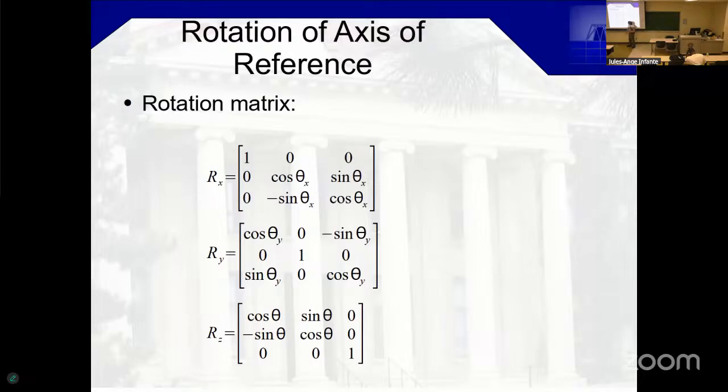So this is theta Z and theta X, theta Y. And this is around on the horizontal plane, but this is on the X plane and the Y plane. Okay, the two vertical walls. So you can rebuild them yourself if you want to compare to verify that we're getting to the same, but it would be a similar type of construction. Okay? And by placing things in the order X, Y, Z, you end up with these three rotation matrices.